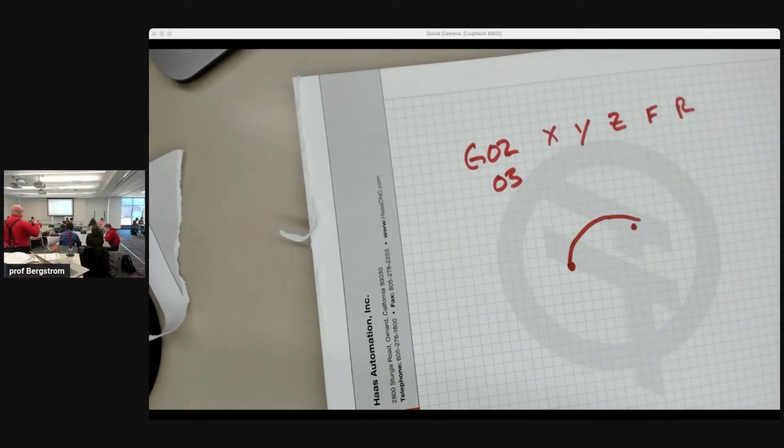And so when you're doing your Esprit or your CAM software, whatever you're using, and it says, do you want to use a canned cycle? There's usually a checkbox. Canned cycle means, do you want us to program line by line each of those pecks, or do you want us to use the machine tool manufacturer's automated cycle for doing those pecks? And it's going to depend. With G code and NC code, there is no standard. Each manufacturer can implement their own code. Most of them are very similar to each other, but there is no standard.